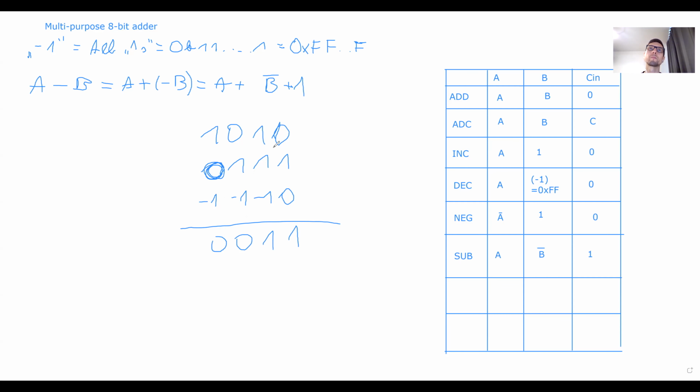But anyway, let's say we had a 2-bit system where we had only a 2-bit adder. When we subtract these numbers, we have underflow, which passes to the next part of the number. So we first subtract the first 2 bits, then we subtract the next 2 bits. So again, we can throw this carry or borrow in the status register. And then when we want to subtract the next part, we take it back and use it. So again, for subtraction, just like for addition, if we add or subtract big numbers greater than what our bit width allows, we first do add or subtract. And after that, we do add with carry or SBC, subtract with carry.